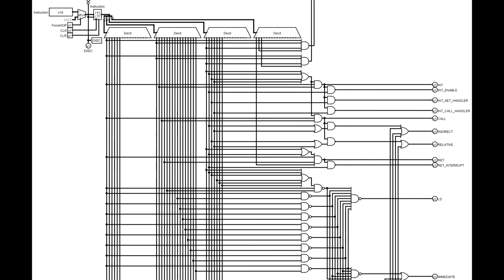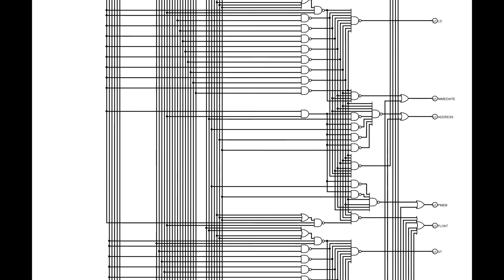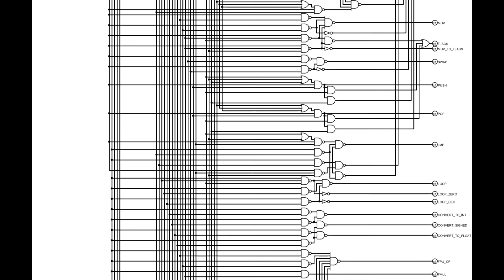In this processor, instructions take at least 2 clock cycles to execute, including the clock cycle needed to load the instruction into the instruction register. The instruction pipeline allows an instruction to be loaded into the instruction register while the previous instruction is executing. It allows multiple instructions to be executed at the same time, but be in different stages of execution. This instruction pipeline will have 4 stages. Each stage of the pipeline starts with a register to store the instruction data in, and ends at the register of the next stage. Each stage, except for the first stage, will generate control signals specific to that instruction.